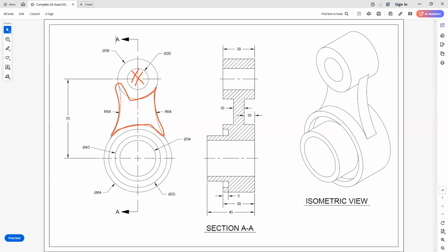So I can either revolve this, or I can create multiple cylinders and join them together and then subtract them, right? So I'm going to approach this, and I'm just going to create this view here, and I'm just going to put a circle around it here. And I'm going to create this part here. And I do have to have a center line, so I'm going to need this line here as well. And then I can revolve this in order to get this shape here.